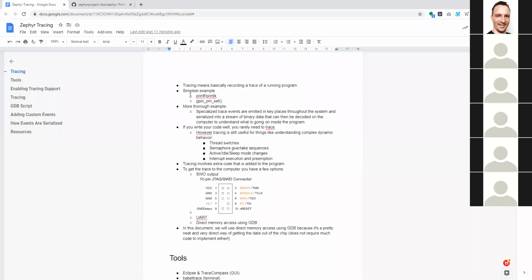The most basic type of trace that everybody's familiar with is simply printing things out on the console. We're not going to talk today about that, but I just want to mention the different types of tracing that you can encounter in embedded systems. So printk, printf, that's the most common thing. You print out something on the console, you print out a variable, and you can see that variable in the console. The biggest drawback with that is that you can't easily process that data. You cannot display it in a tool that is designed for displaying traces, so it becomes a little bit limiting in that sense.